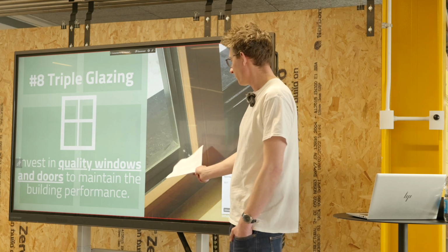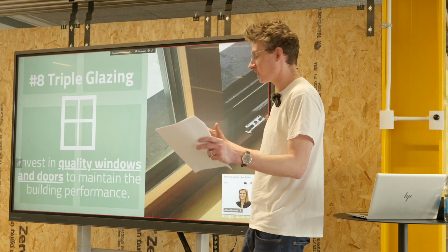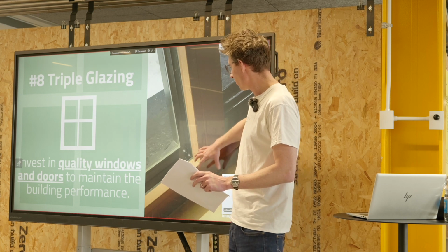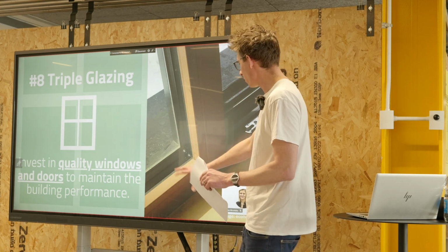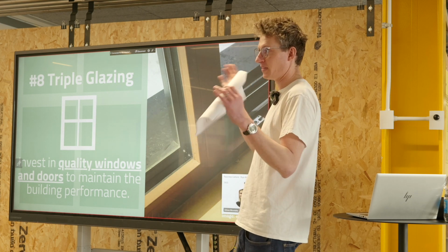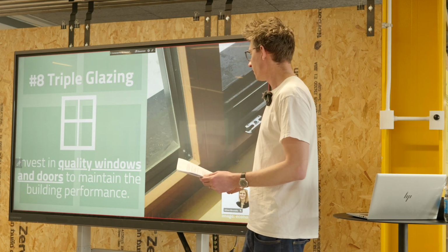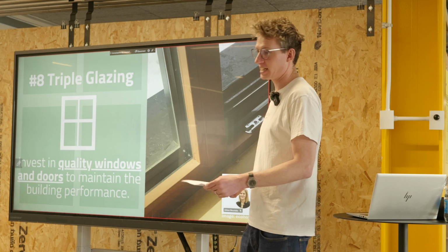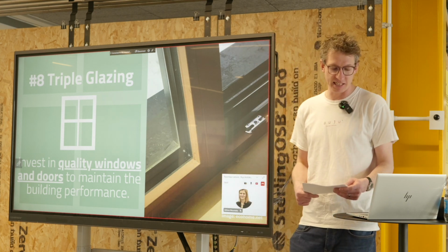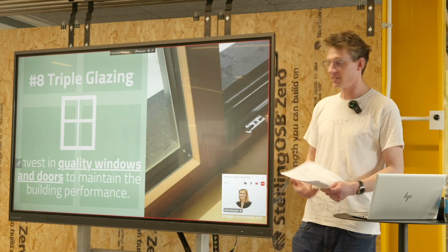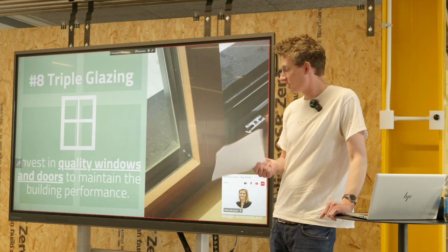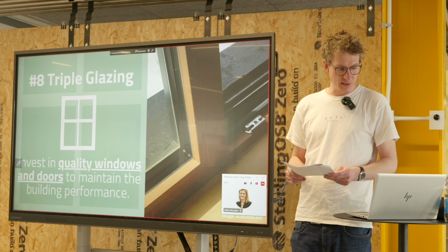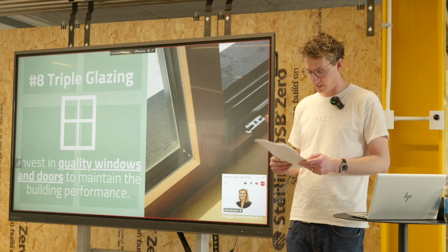And so quite often you'll get a supplier who provides a very efficient glass, but actually if it's not within an efficient frame, or it's not been put in the wall in the right place, or it's not got a good install value, you actually lose huge amounts of heat around the edge of the window, which often doesn't necessarily get the headline of the actual U value of the glass. So there's those 4 different U values that need to be considered, and the analysis of the window installation is another part of it, which is really important when you're trying to create those efficient designs.